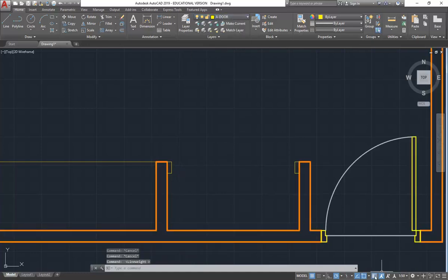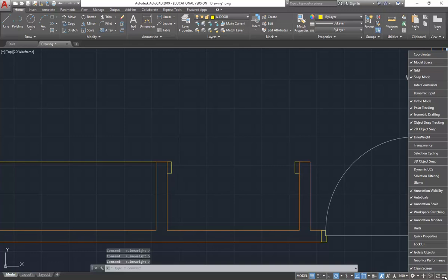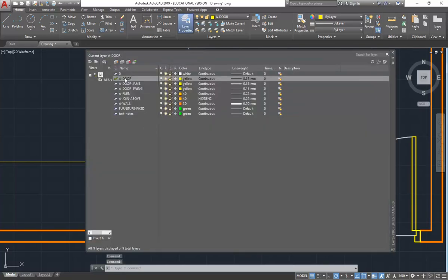And I haven't shown you that the line weights can be turned on down here, if you want to see them. Remember that little button in the bottom right corner. If you don't see the line weights option, it needs to be ticked there, and then this little button here will turn on and hide and unhide your line weights. And that's good to check because they haven't gone in properly, so I'm going to just go and make sure that they're working. Yeah, door jamb, okay, 0.35.